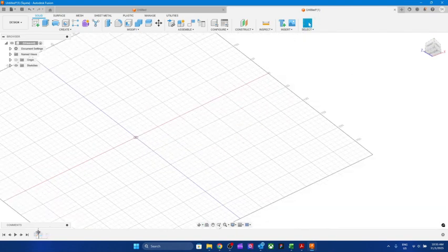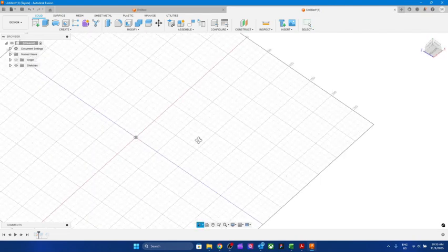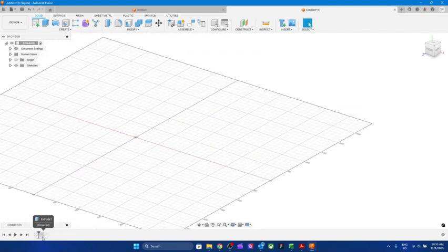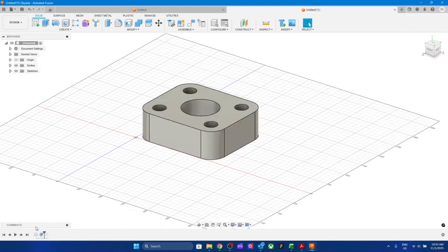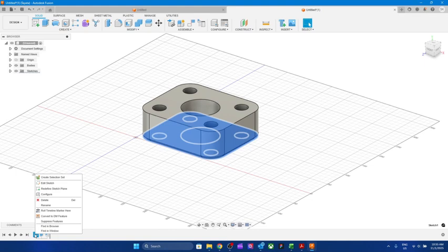If I want to go back, I cannot see the sketch, you see, because a sketch is consumed within this extrude and that's why I will have to get my sketch. So going back to your question, if I want to edit the original sketch, which is this one, I can simply right click and edit sketch. That's one option.